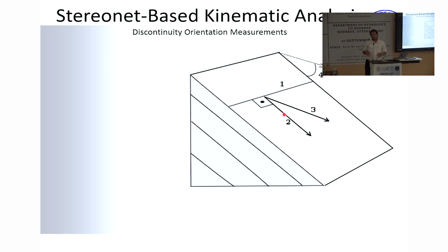Okay, so for example, if this is north and a plane is slanting like this, then its orientation would be say 45 degrees towards north. This is horizontal, it is dipping 45 degrees towards north. Is that clear? So if that is north, this is east, I hope. So this is dipping 45 degrees towards east. If it is less, then maybe 10 degrees towards east.